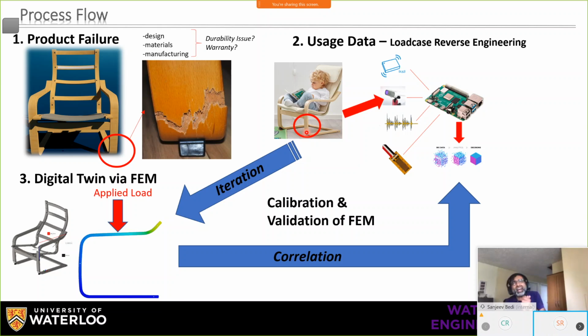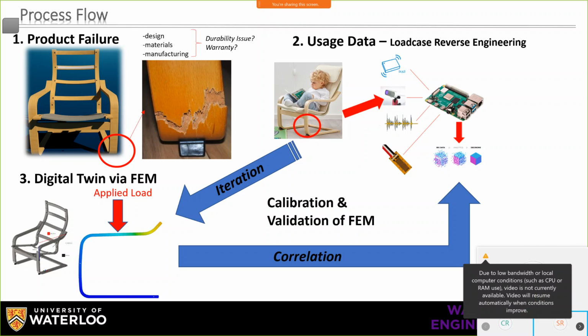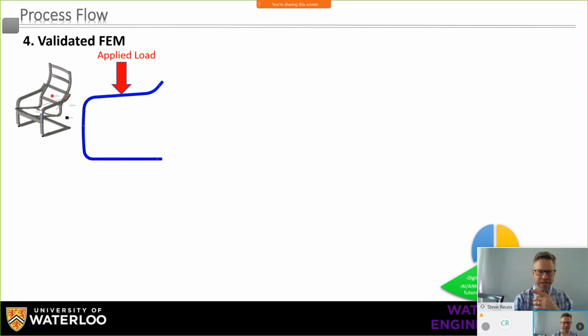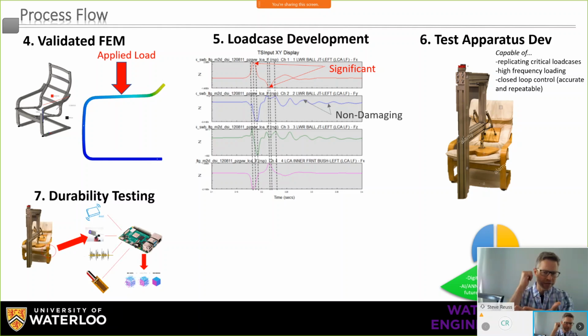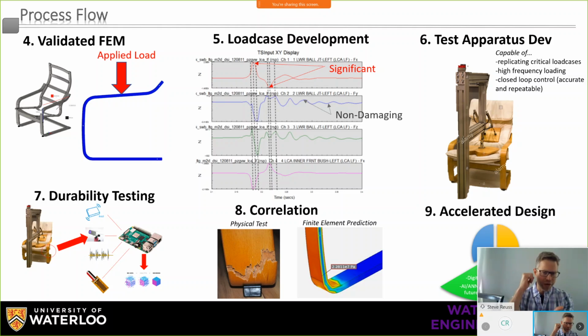Like, in situations that we've gone through, it's actually step 6 or whatever it was, where you had a really well-defined test apparatus which showed, I'm applying this load and this is the resulting strain. That's the kind of correlation data, the test apparatus, that is often needed to back out the material properties that really are probably in play.